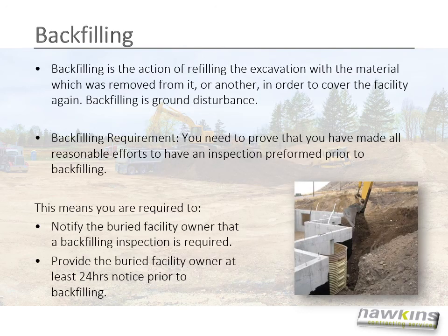Backfilling is the action of refilling the excavation with the material which was removed from it or another in order to cover the facility again. Backfilling is ground disturbance as well. An important backfilling requirement is that you need to prove that you have made all reasonable efforts to have an inspection performed prior to backfilling. This means you are required to notify the buried facility owner that a backfilling inspection is required and provide the buried facility owner at least 24 hours notice prior to backfilling.